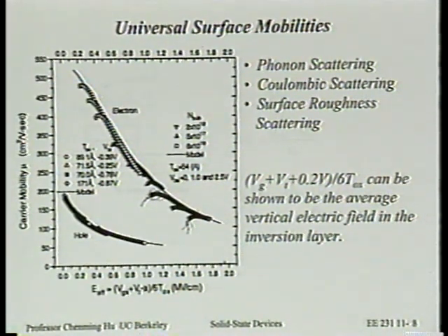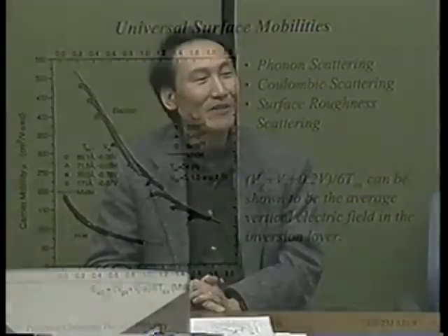JFET, no one had any argument, not even from me, that it is a bulk device. If you don't know what JFET is, no problem. Don't bother to look that up. But JFET truly is a bulk device. It has no surface. And when we look at that, it's an order of magnitude difference in the noise, because it does not have the surface effect. So when we look at the P plus and N plus, I was hoping the number is much smaller than 5. True, I can see that.